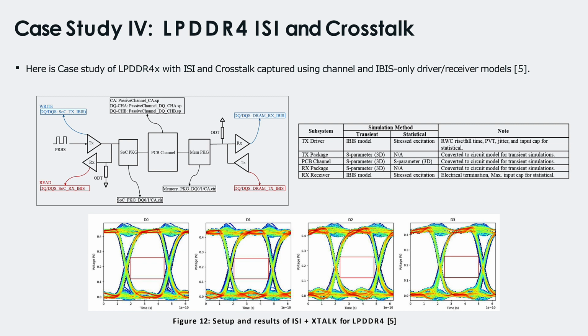So one technique explained in this paper is that you could define a reasonable worst case that stresses your eye at the receiver side. So let's say we pick the DDR interface, and then from the JEDEC specs, you pick the worst input capacitance for the RX. And then you also have some TX input that you would get from your vendor. It may not be a model, but just a jitter number or rise time. You do a mix and match of those environments to make a stressed eye. And as long as the channel that you design passes that specific stressed eye, you can assure that, not idealistically, but you are at a good starting point. So you can start with that as your channel design.